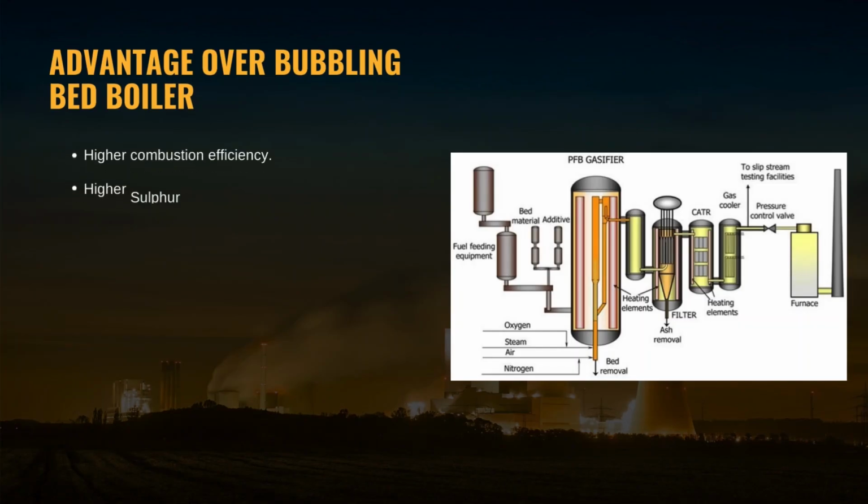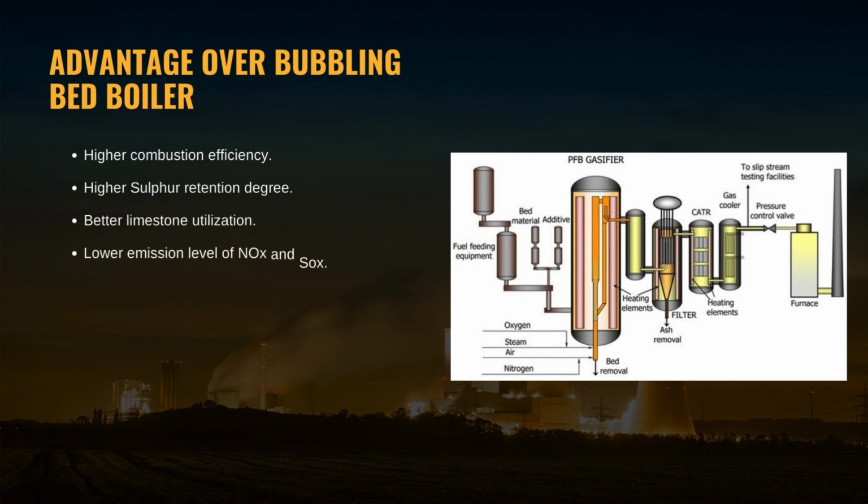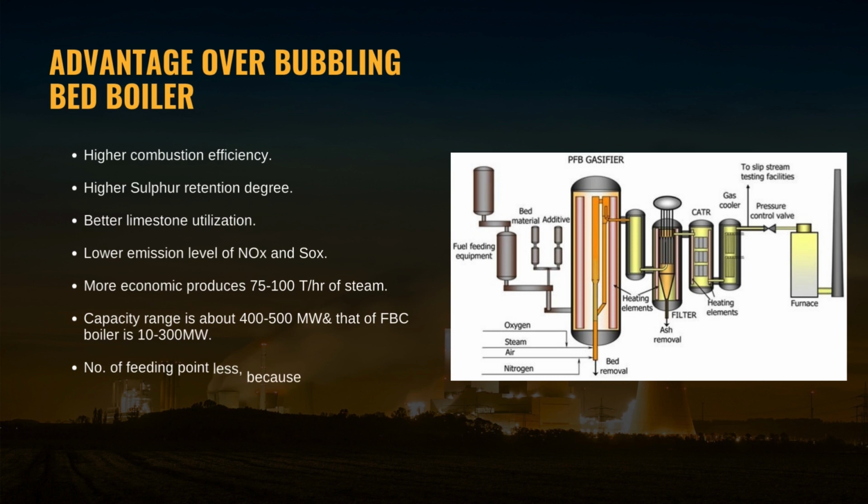Major performance features of the circulating bed system are as follows. It has high combustion efficiency. Sulfur present in the fuel is retained in the circulating solids in the form of calcium sulfate and removed in solid form. The use of limestone or dolomite sorbents allows a higher sulfur retention rate, and limestone requirements have been demonstrated to be substantially less than with a bubbling bed combustor.